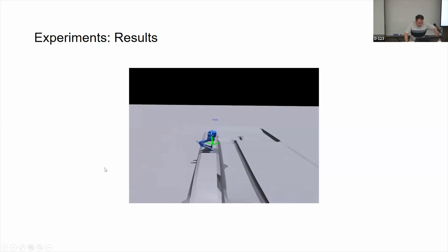So here what we can see is that for some reason, on that kind of narrow platform, the controller of the Cassie robot tends to look towards its left side. So actually, I think this is quite an interesting result because we would not necessarily have found it if we just manually tested the controller on handcrafted terrains, because this behavior actually only happens when this narrow platform has a specific width.